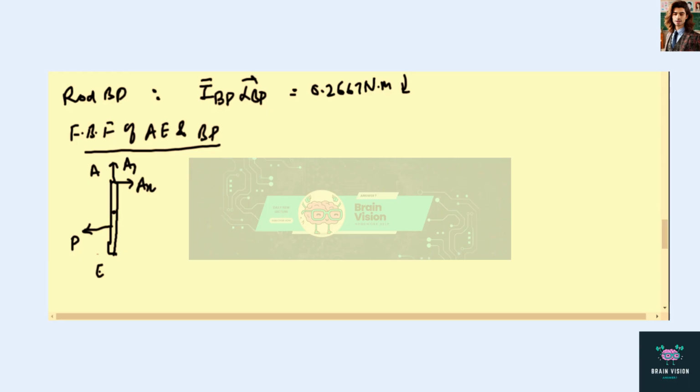This is the center of mass, so here weight of AE will act. It will experience force due to its motion, mass of AE into acceleration of G, and due to rotation, IAE into alpha AE.